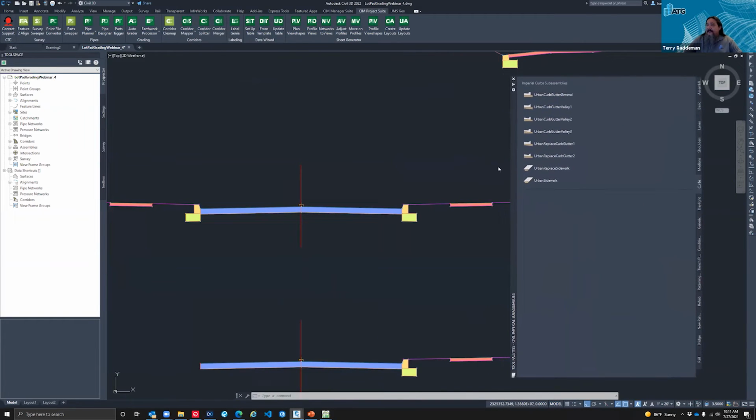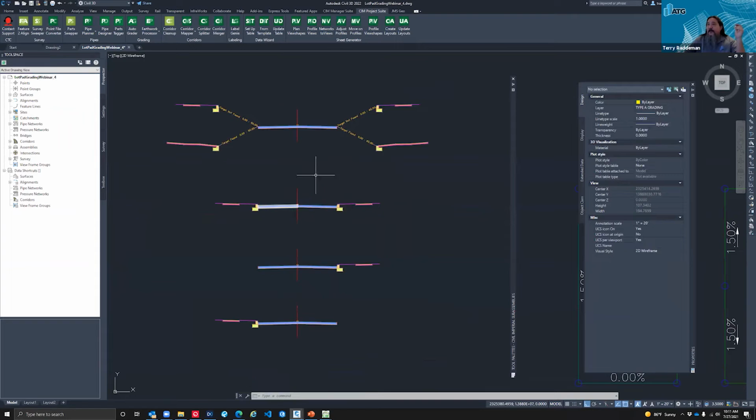So with that, for our subassemblies to build these out, we can look at some of the components on here, and we'll look at some of the conditional statements and targeting. Right now, when we start building subassemblies, most of the time we'll have half a road on each side, a full road segment, and a segment that we can use for our conditional statement, or conditional targeting.